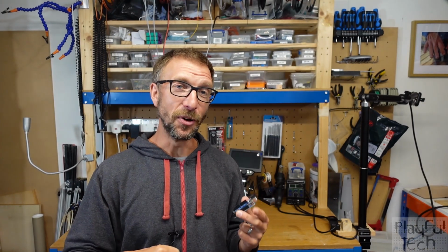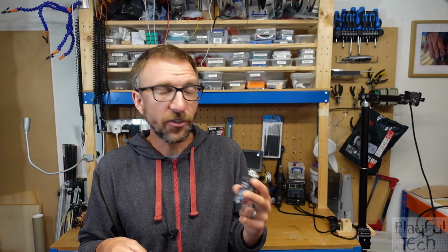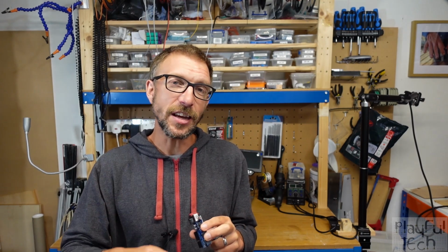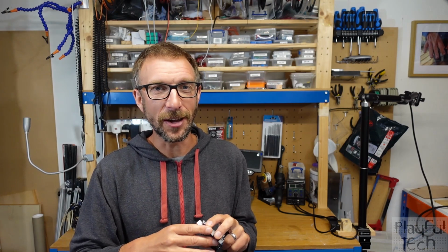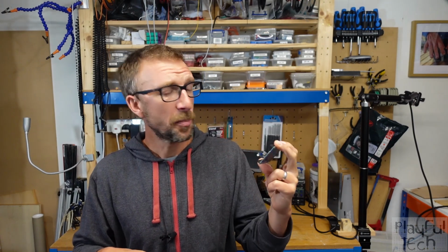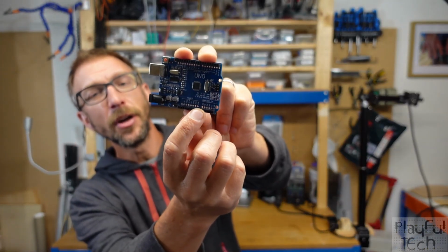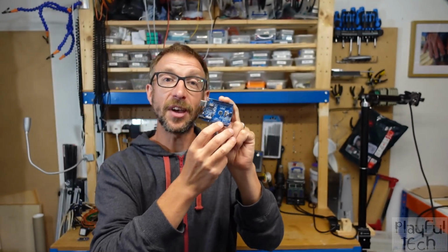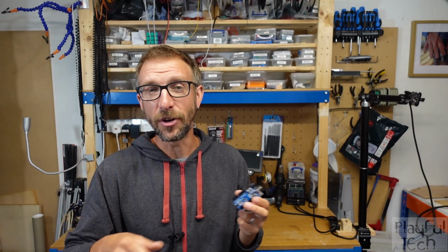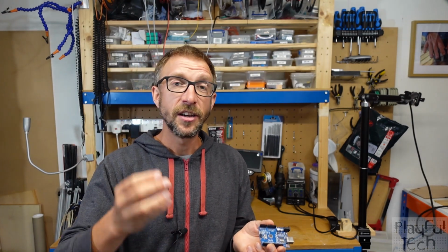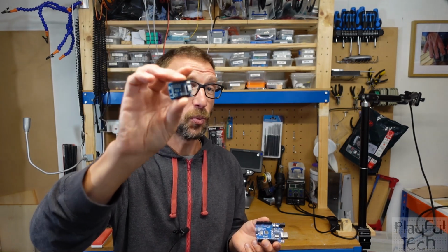Now, some GPIO pins also allow you to read an analog input. So a value from a light or a temperature sensor, or inputs from a potentiometer or an analog joystick. And this is done with a part of the chip called an ADC, or an analog to digital converter. Now, on an Arduino, the pins that can be connected to the ADC are those labelled with an A. So an Arduino Uno has 6 analog inputs, A0 to A5. The ESP32 has 15 pins that can read an analog input, whereas the ESP8266 only has 1.